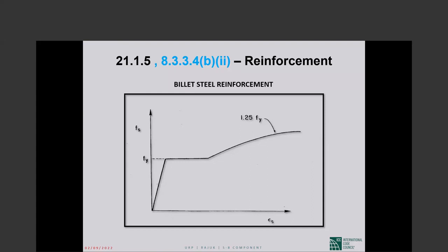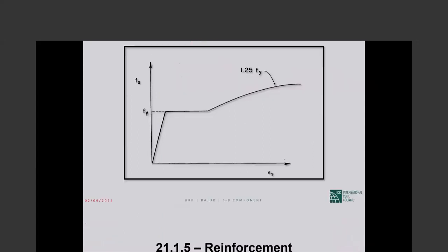Now the 125% differential between tensile and yield strength is something many steels cannot meet. So this requirement has also been a significant screen in many reinforcements. If, in Bangladesh for instance, you want to import reinforcement from somewhere else, China, Korea, you may find that the reinforcement doesn't meet this requirement, and then you cannot use it.